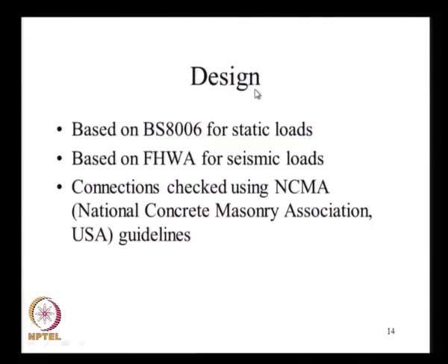And the design itself is based on several codal provisions because of the site conditions. For most of the designs, the BS 8006 was used for the static loads, that is for checking for the lateral stability and then internal stability, both under external forces and internal forces.